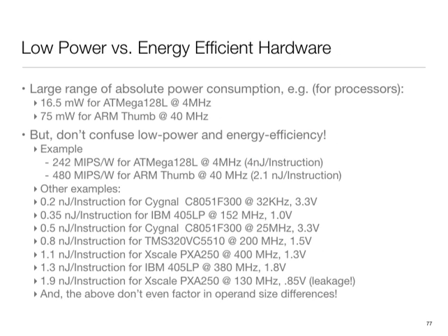One other point I wanted to make in this realm is that from a system designer perspective, when you are looking at your choices of parts, there's a difference between low power and energy efficient, and which one is better suited depends upon your application. It is something you have to be aware of. I may have processors whose power consumption is low, but by the time you look at their clock rate and architectural capabilities, the time they take to do the same work may be in the opposite direction.